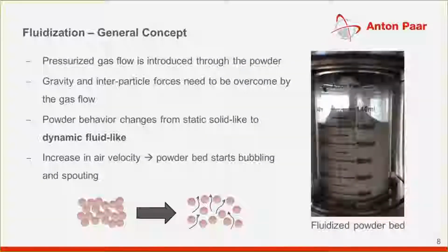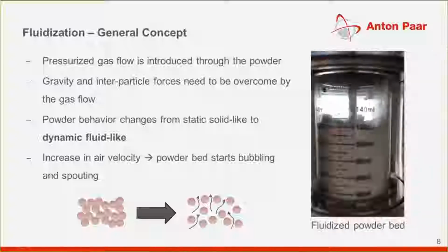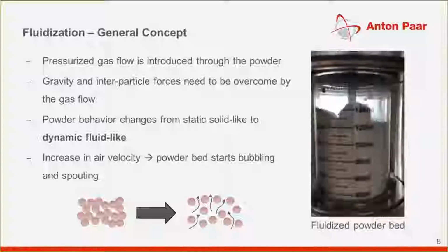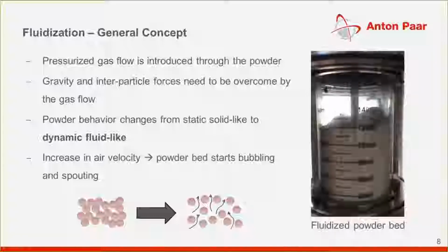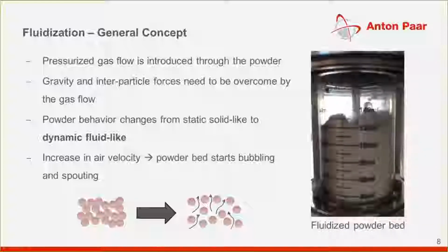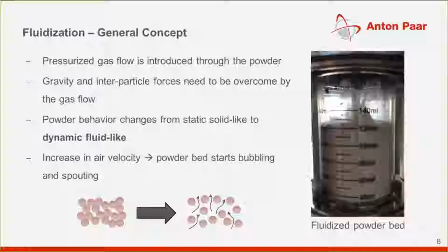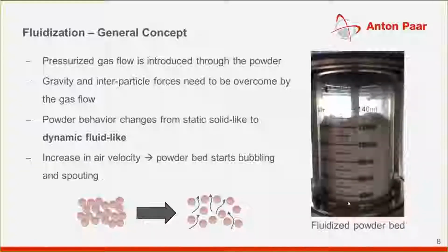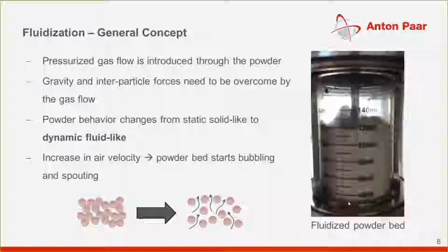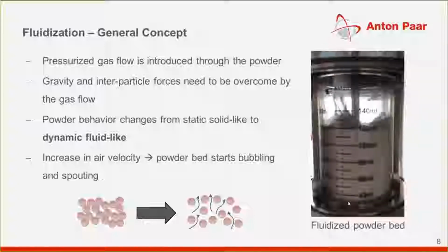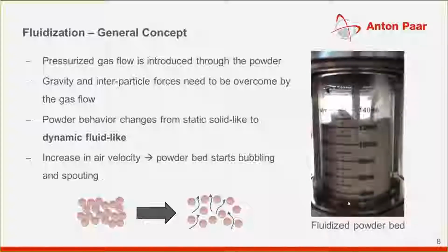Before going into fluidization properties, we have to have a look at what it means to fluidize powders. In fluidization, pressurized gas is introduced through the powder bed. If the gas flow is strong enough, the gravity and interparticle forces are overcome, which results in a dynamic, fluid-like behavior. We can see on the right side a video showing an example where the air is flowing through the powder from the bottom of the cell. You can see here on the bottom, and this fluidizes the powder. We can also see that with a strong enough airflow, the powder even starts to bubble and spout as if a liquid were boiling.